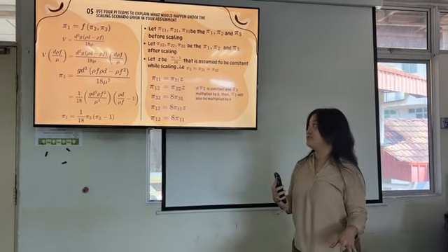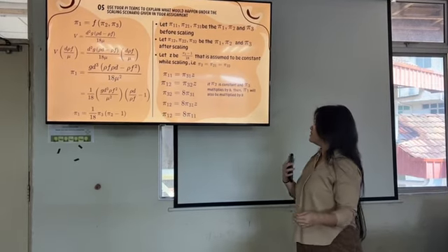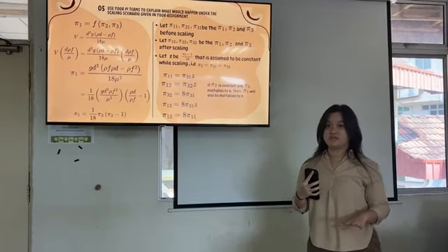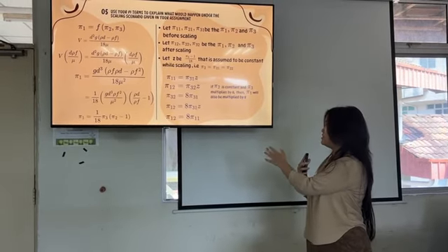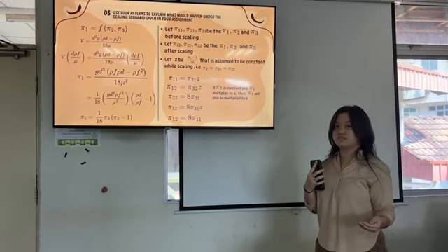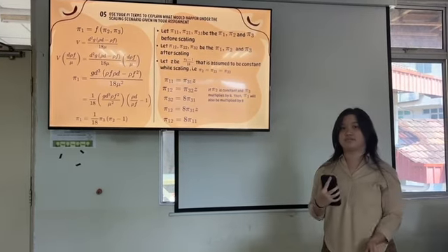And we're going to do the same thing, which is isolate some of this and represent it with a variable z. And we're going to assume that's also constant during scaling. So from our previous calculations, we know that pi 2 will be constant. It's not affected by the scaling, and we know that pi 3 multiplies by 8. So from the simplified equation that we've gotten, we can just assume pi 2 remains unchanged, and we can assume that pi 3 multiplies by 8, and if you simplify that, then you can see that pi 1 is also multiplied by 8.